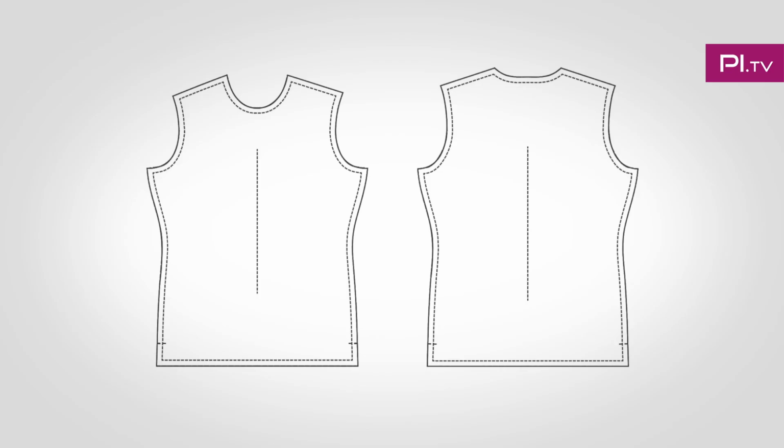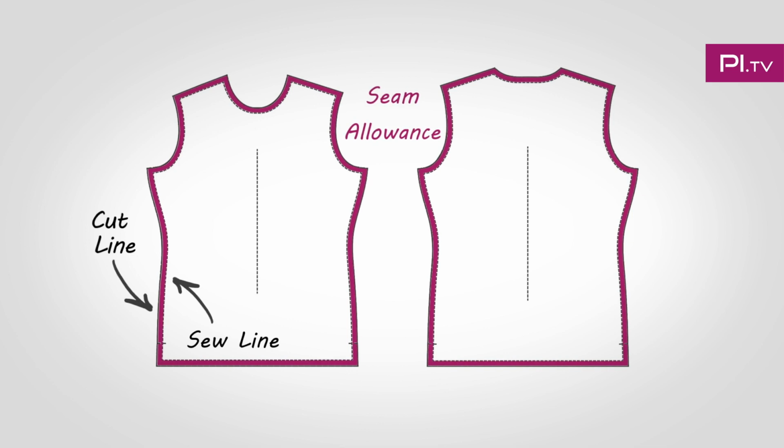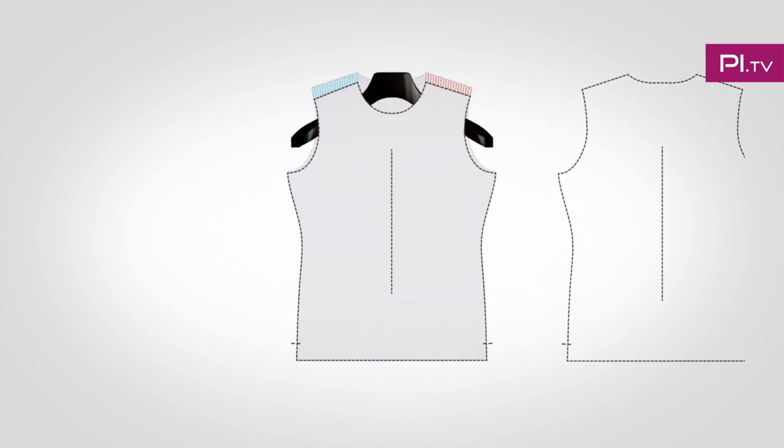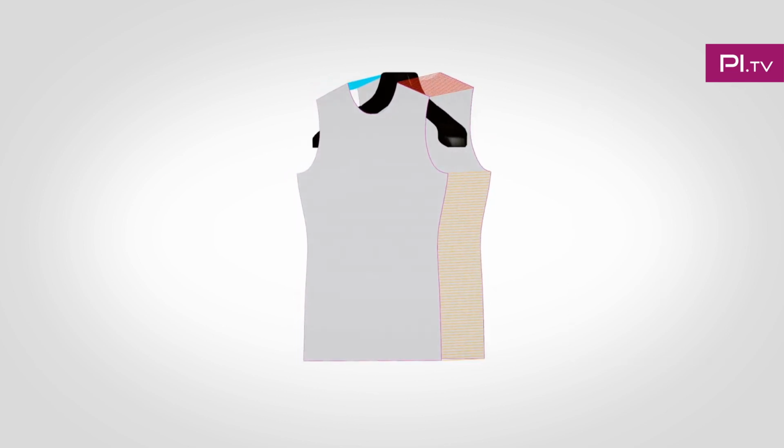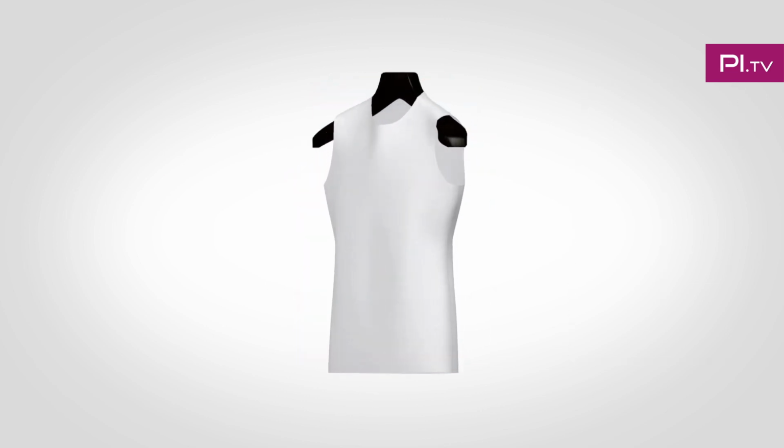For a 3D simulation, what's really important is that you have a great sewing line defined on your patterns. Now, some of our friends in industry who have been working on patterns for a very long time don't necessarily concern themselves with the sewing line as much. We see things like swapped seam allowances, which is okay, as long as that sewing line is still there and you can identify it and you know where to stitch your patterns together in the 3D environment. Once you have that sewing line clearly defined, inside of that sewing line is where your 3D mesh or your virtual mesh will be created to apply the physics to turn your patterns into cloth in the virtual world.